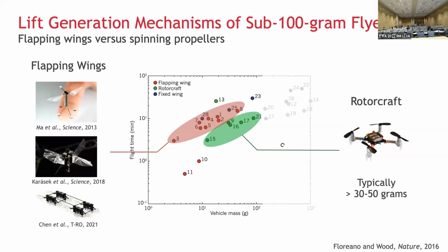Right? This, of course, has lots of explanations. It's rather complicated. But simplistically, I can nail this down to two important factors. The first one is about the Reynolds number and the mode of lift generation or thrust generation. The motion of flapping wings, which is like insects, actually helps improve the aerodynamic efficiency by using what they call unsteady aerodynamics.